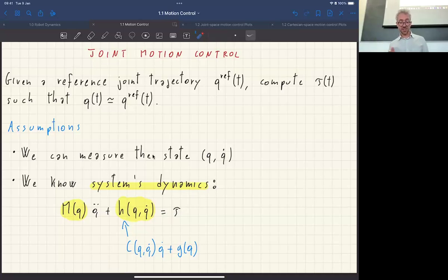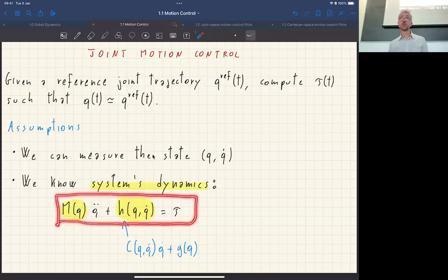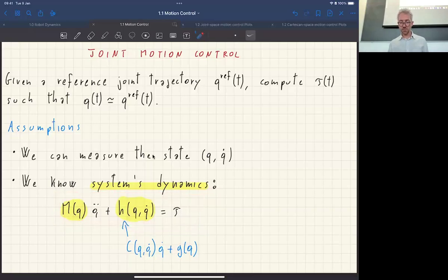And actually, the most important thing that we are not modeling here, but that plays a big role in robot dynamics, is joint friction. Of course, we could add a term, like in here, which is, I don't know, D q dot, which accounts for viscous friction. You can estimate viscous friction on the robot, it's not a problem.